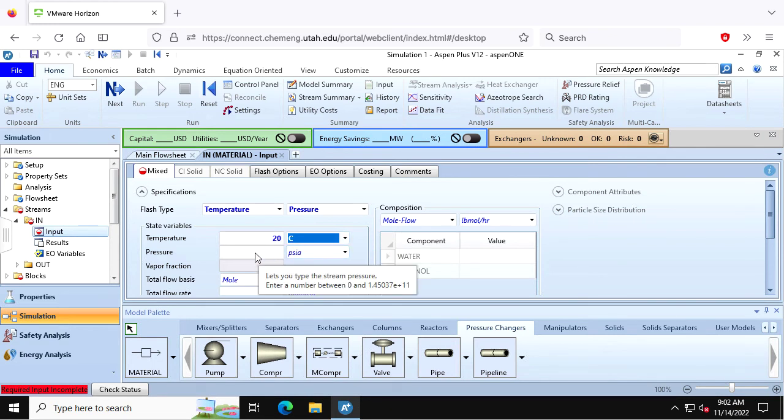You weren't given a pressure, but what I'm going to do here is, this would be like after the pump, so we're just focusing on the pipe. I'm going to give it a very high pressure because I want it to calculate the pressure drop. If I said like 15 psi, already you know that because it's at the bottom of that 120-foot rise, it's got to be more than 15 psi. How many psi would it be at the bottom of a 120-foot column?